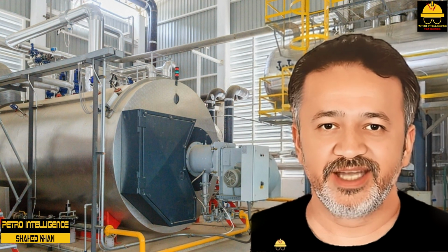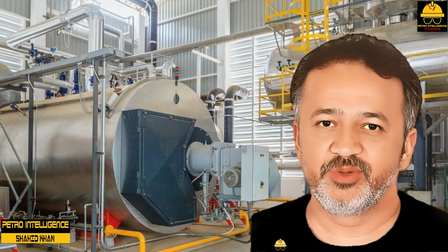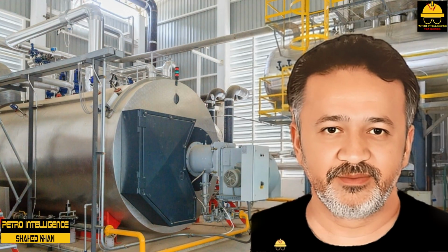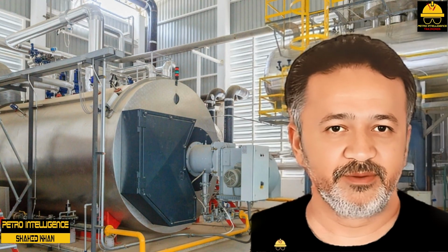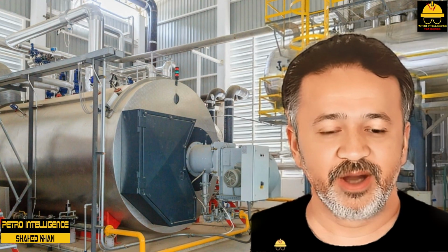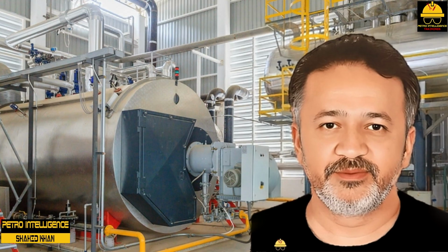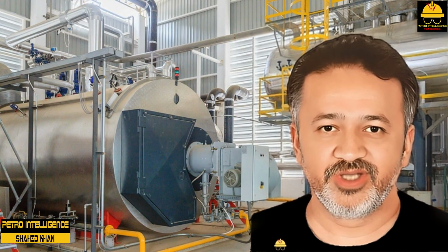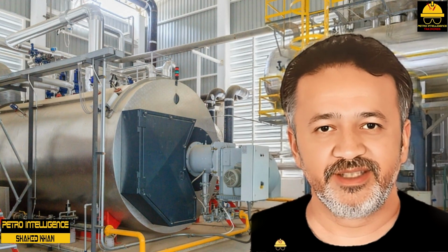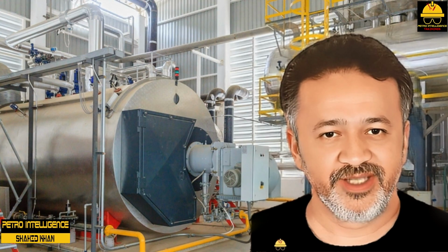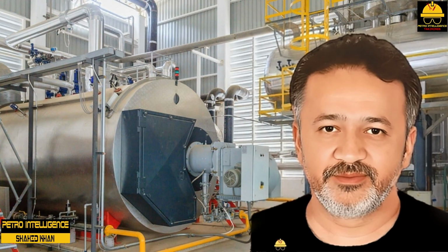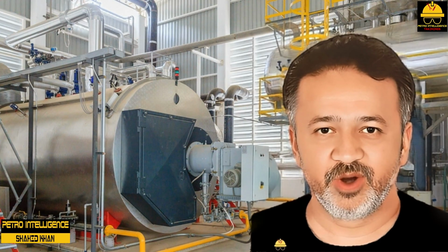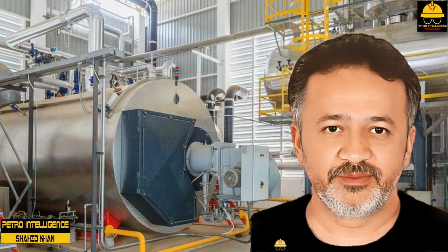Steam systems designed to reclaim steam use steam traps to remove condensate. Steam traps are grouped into two categories: mechanical (inverted bucket steam trap and float steam trap) and thermostatic. Thermostatic steam traps are cheaper and selected more frequently than any other. They respond to the temperature differences between condensate and steam. A common thermostatic trap design is the bellows trap.